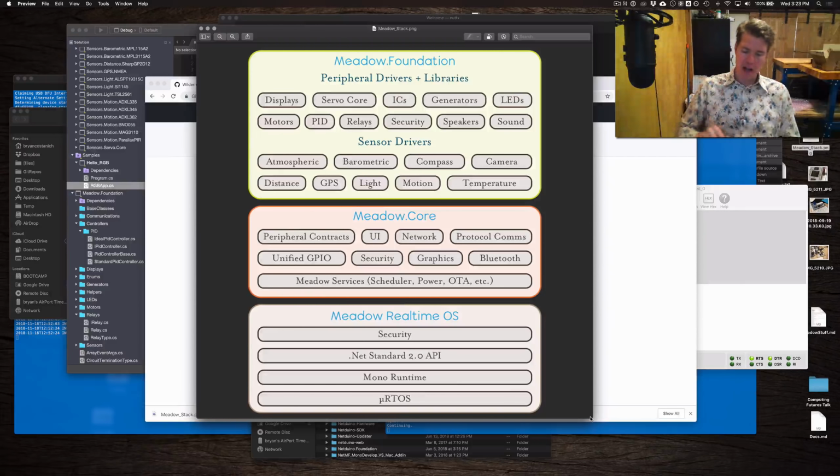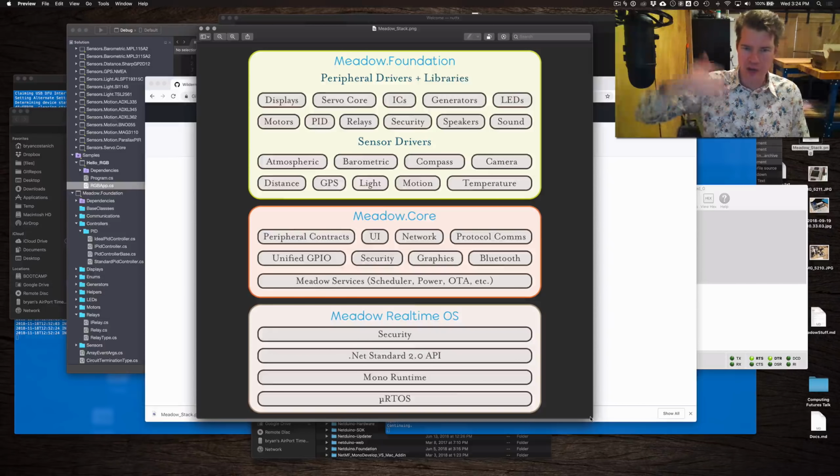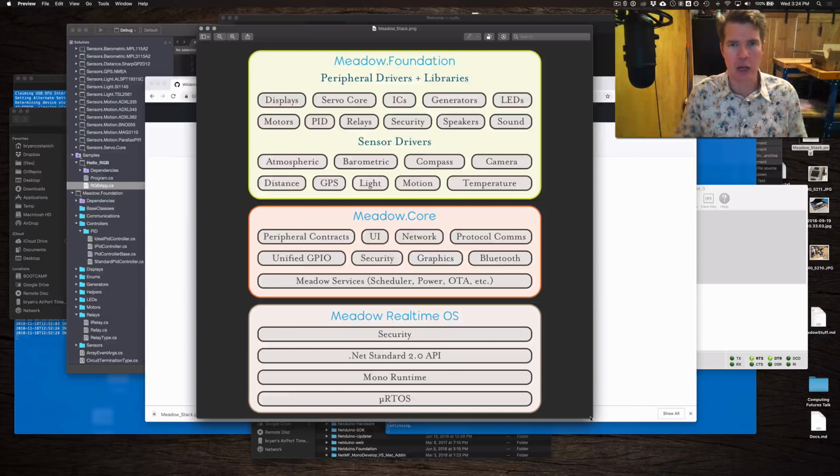So we have modified the Mono runtime so that it lives on our NuttX install, and our NuttX package is very heavily modified for our hardware, and it's not just configuration stuff. We have to expose certain hooks so that exceptions, for example, in .NET are handled really well, and have native support throughout the Mono stack. We've also changed the way that we handle memory and the way that memory is accessed, making that much more friendly to a managed runtime.